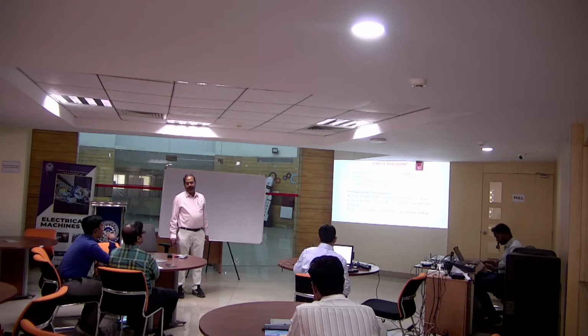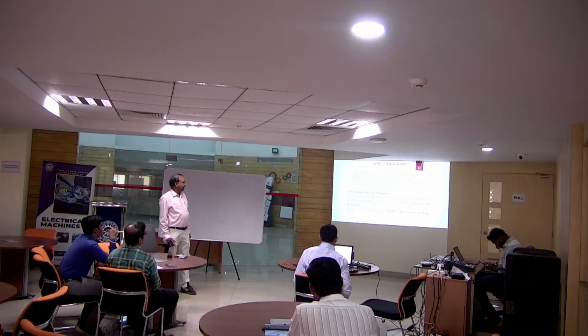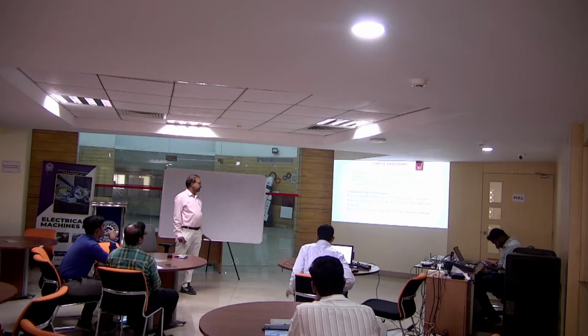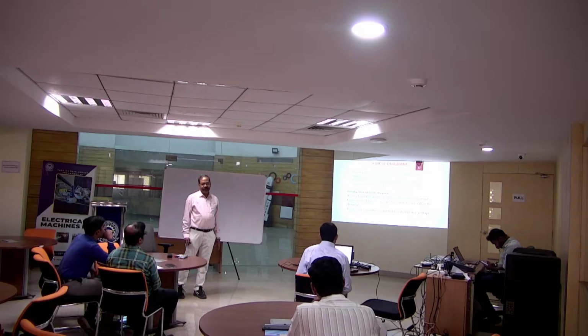And its no load power factor is cos phi 0. These two things, phi 0 and I 0: phi 0 is the angle, so that cos phi 0 is the no load power factor and I 0 is the no load current. These two data we require, and also from the block rotor test, short circuit test, we take the short circuit current,